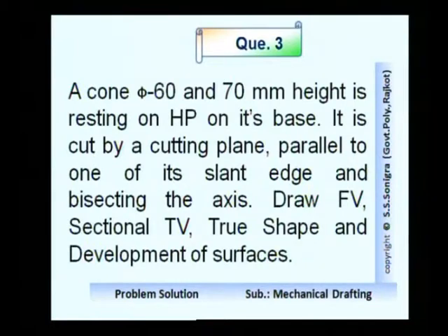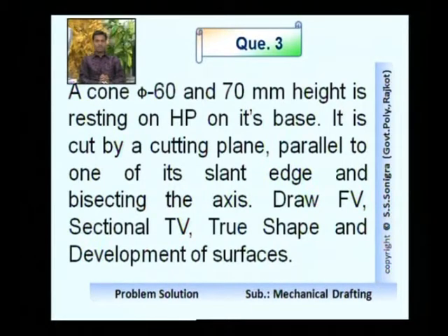Now next problem. A cone of diameter 60 mm and height 70 mm is resting on HP on its base. It is cut by a cutting plane parallel to one of its slant edges and bisecting the axis. Draw front view, sectional top view, true shape and development of the surfaces.